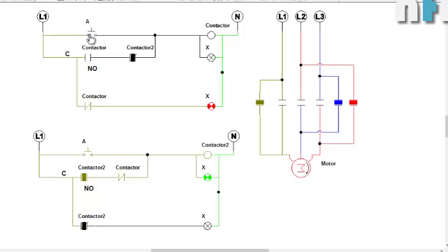It's quite easy. That was the project which I did. I have made a video in which we did this direction control using 2 limit switches. So similarly we can make it for a DC motor. In a DC motor we worked on 0 volt and 24 volt. I don't have a DC motor in my software, so I cannot show you the proper simulation. But in case you want it for a DC motor, you can send me an email or comment below this video. I can send you the same tutorial. It cannot animate, but I can show you how it works for a DC motor as well. That's the same principle of relays. We do not require contactors for a DC motor.